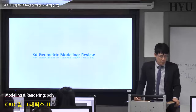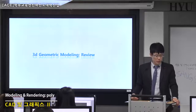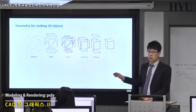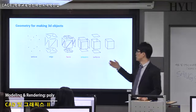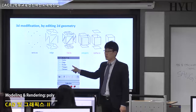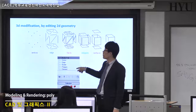3D geometric modeling, review from last week, okay? Today, we experienced some control over vertices, edges, especially polygons. By using this one, editable poly, okay? We can control vertex, edge, and polygon.